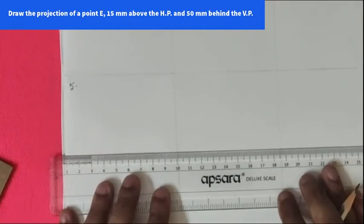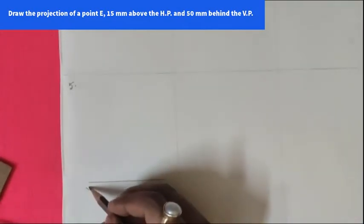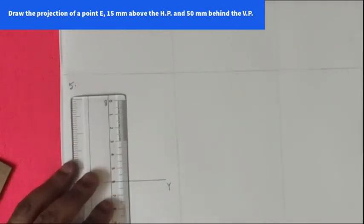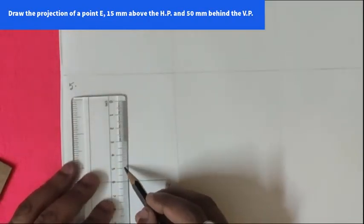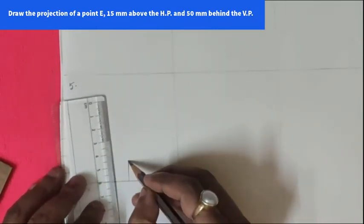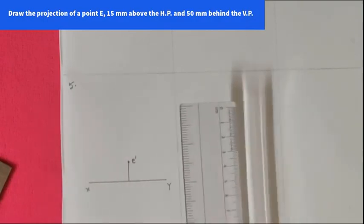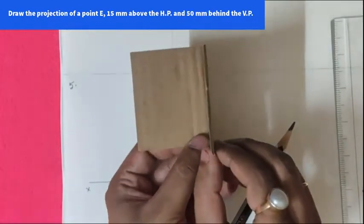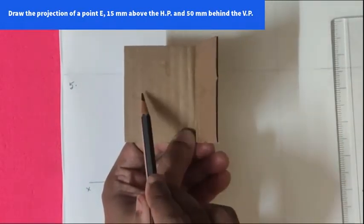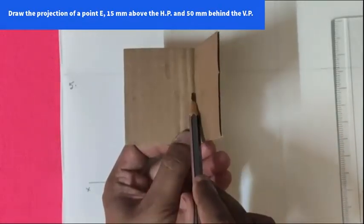Let us draw the XY line first. This is our XY line and it is given 15 mm. So 15 mm we have the first point, that is your small e dash. Clear? Now see the top view. What is given is that it is 50 mm behind the VP. So it will be projected where? Here. Distance how much? 50 mm.